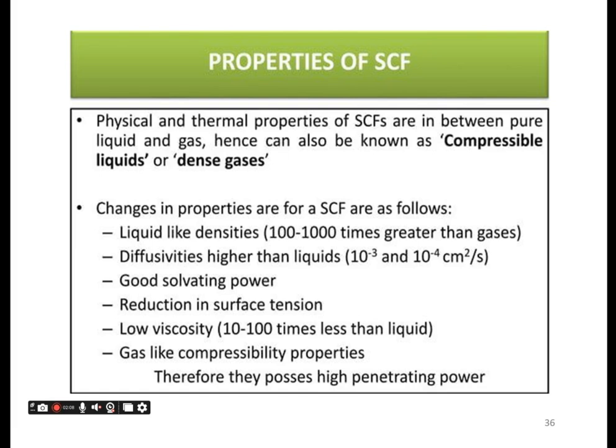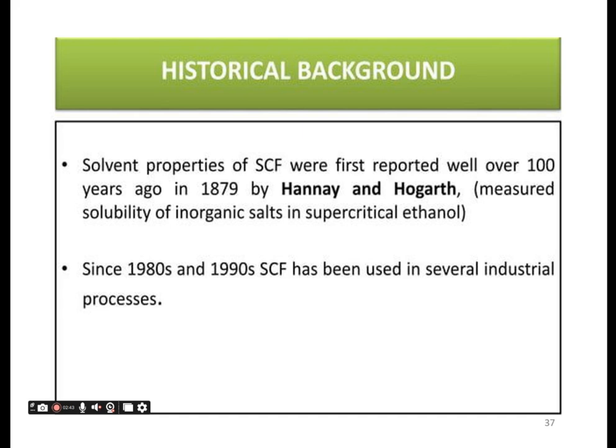Then what are the properties of this supercritical fluid? The physical and thermal properties of SCF are in between those of pure liquid and gas, hence it is known as a compressible liquid or dense gas. The properties of SCF are as follows: liquid-like density, 100 to 1000 times greater than gases; diffusivity higher than liquid, that is 10 raised to minus 3, 10 raised to minus 4; good solvating power; reduction in surface tension; low viscosity; and gas-like compressibility. Therefore, they possess high penetrating power.